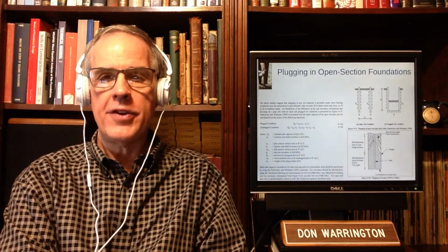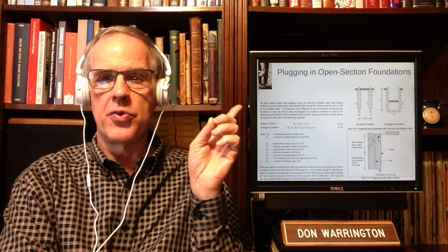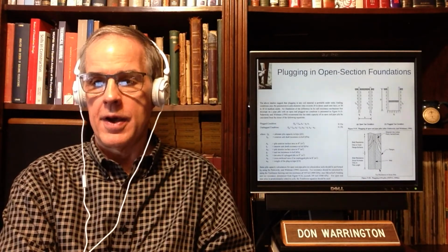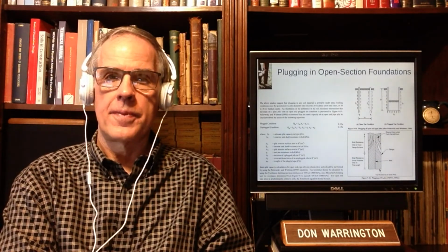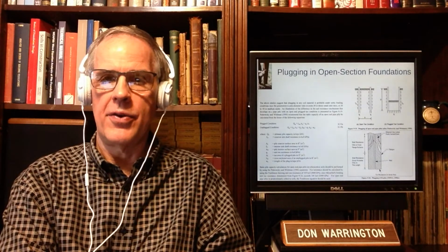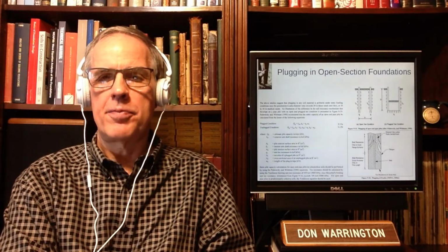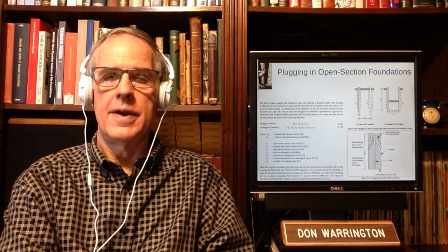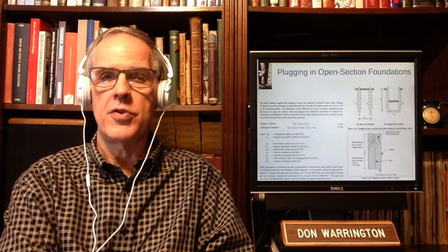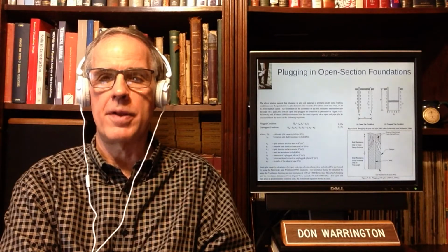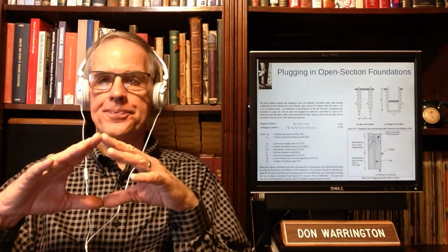Open-ended pipe pile plugging takes place at the toe. H-beam plugging is a whole different phenomenon, in that it takes place along the shaft of the pile. I have a little shot in the corner of this slide which shows one of the people who used to work for me actually pulling a plug out from the side of an H-beam driven in the yard. And basically the way you deal with H-beam, if you assume you have H-beam plugged, let me just back up.